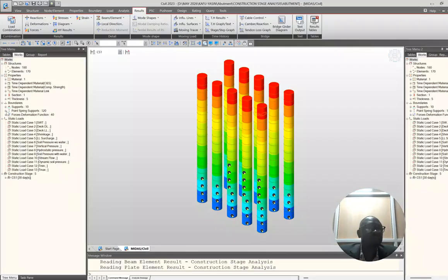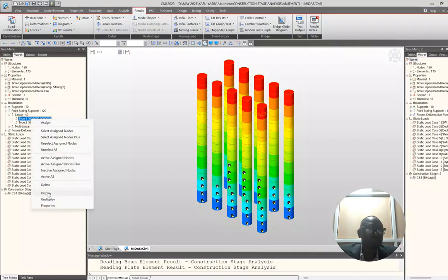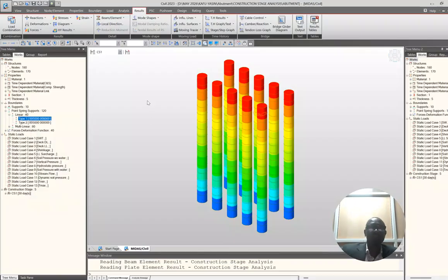So I think to have it look nice, what I would do is to first remove the spring constant. So this is my first stage. I construct it. Normally you have to put the boundary conditions. Self weight will be at the loading stage. You have the self weight, then the boundary condition must be put in place, and then the elements or the subgroup, which will be the pile.